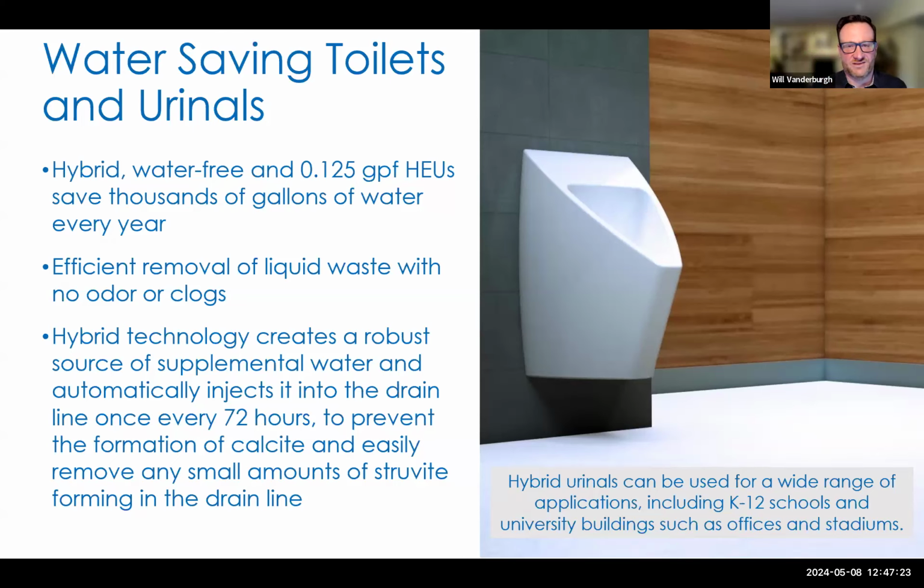I will offer the caveat that I always do with water-free technology. It really has to be employed on new construction where you know exactly the drain slope and drain sizing behind the wall, and that you can be assured that all of the plumbing drainage behind the wall is all plastic, because metallic systems are not able to carry away that concentration of urine without rusting out. Copper, for instance, copper drainage will wear out extremely quickly with all that uric acid going through it.